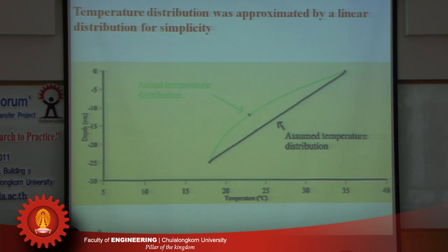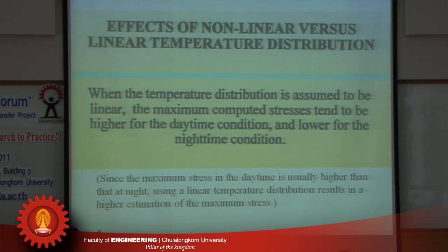We also look at the simplification. Typically, the temperature plot is a nonlinear plot. To simplify the computational procedure, it's simplified by a linear approximation. What happens if we assume it to be linear and we calculate the stress? We found out that when the temperature distribution is assumed to be linear, the maximum computed stress tends to be higher for the daytime condition and lower for the nighttime condition.